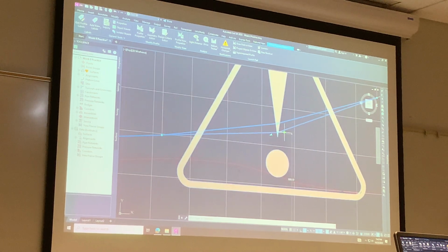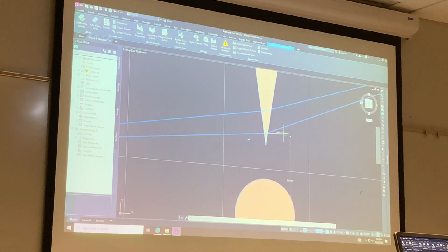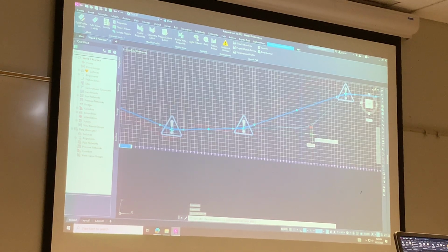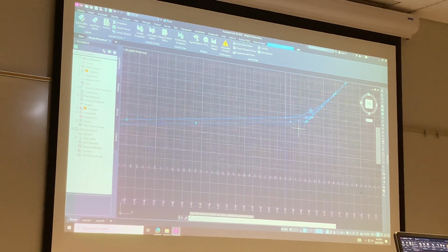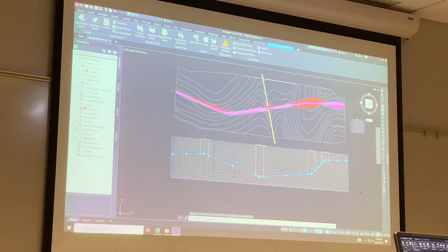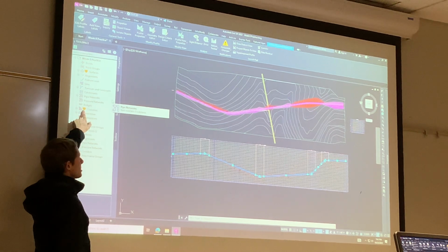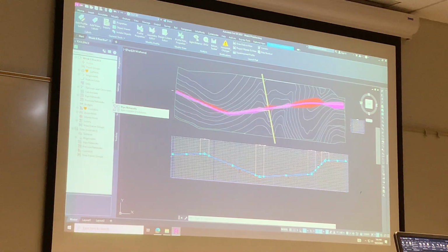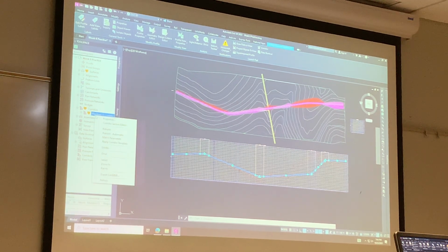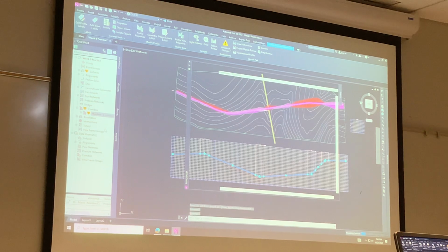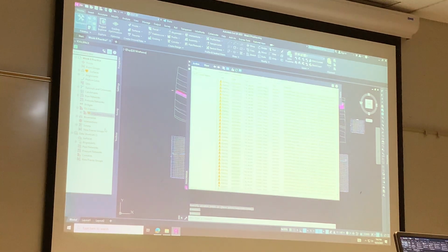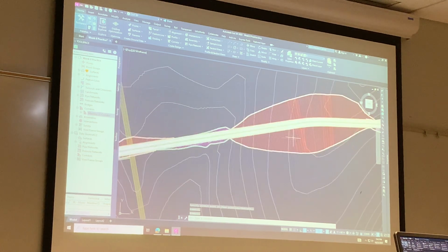Click on the arrow that points up and to the right, and drag it over this way until it's really deep into the hillside, and then place it. Now you'll notice it didn't give us a warning, but there's a little exclamation mark by corridors. If you've changed that profile, open the corridors, right click on mainline CL corridor and rebuild it, you'll see it got wider.